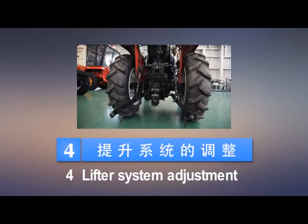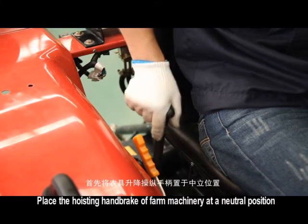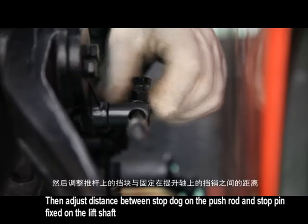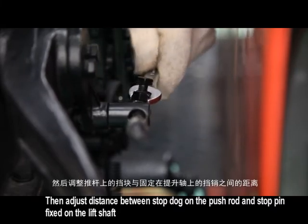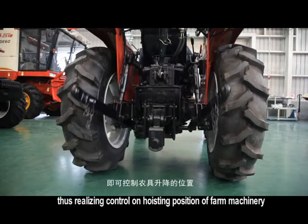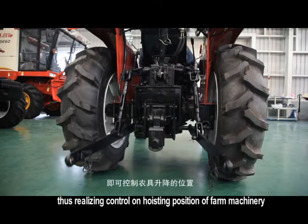Lifter system adjustment. Place the hoisting handbrake of farm machinery at a neutral position. Then adjust distance between stop dog on the push rod and stop pin fixed on the lift shaft, thus realizing control on hoisting position of farm machinery.